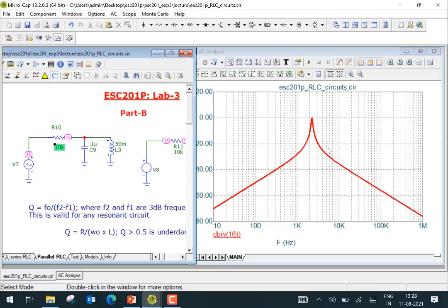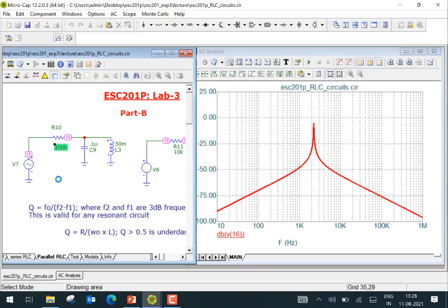All right, so we can see it becoming sharper here, right? And so note that the Q factor is higher, and now it's rejecting the other frequencies far more as compared to the center frequency here. So we can make it even sharper by increasing to 100K here. Now it will just pass the center frequency, and all other frequencies that you see here are getting sharply attenuated. So you can measure the Q, and depending on the kind of attenuation that you want over the other frequencies, you can then decide on what value of Q is suitable for you here.